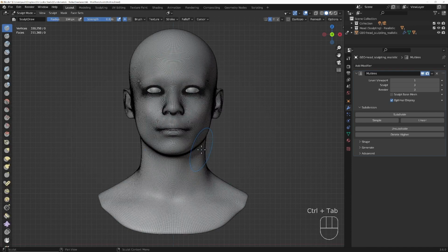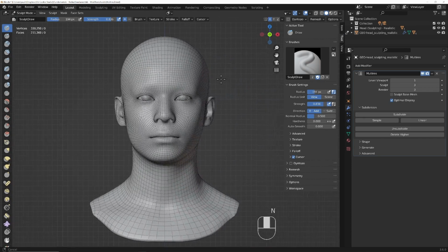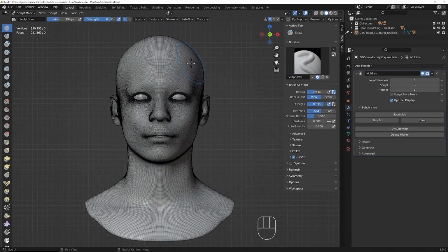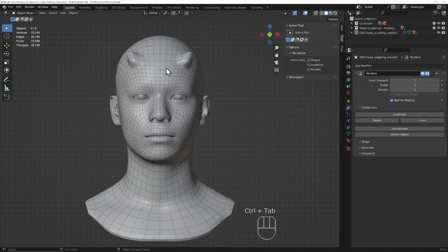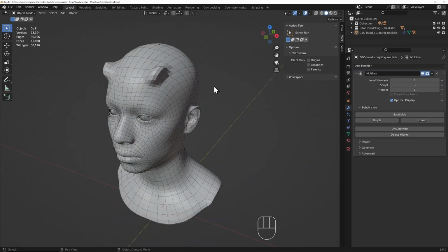We won't go too deep into sculpt settings, but it is important to point out a few things while we're here. For example, I've set the mirror function to X and I've set the sculpt draw radius to 50. Now when I draw on the surface, the mesh will be deformed on both sides of the X-axis. If we toggle back into object mode, because the viewport level is still set to 1, the deformation will also be shown, but with reduced resolution.